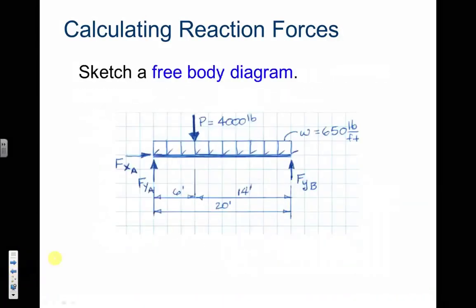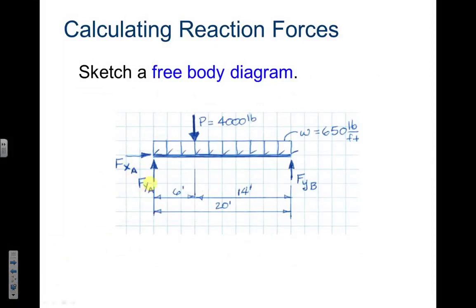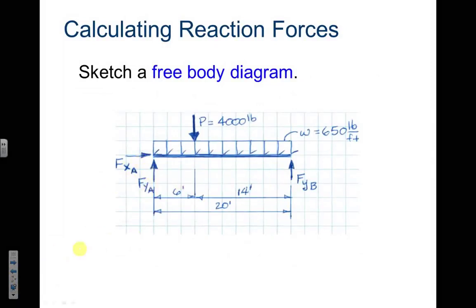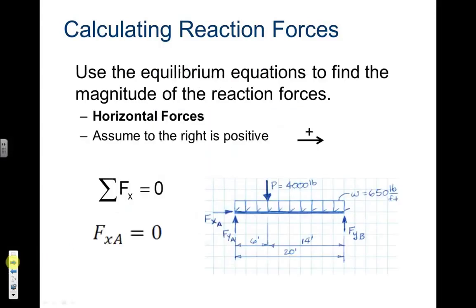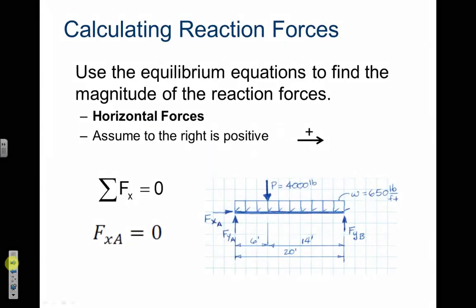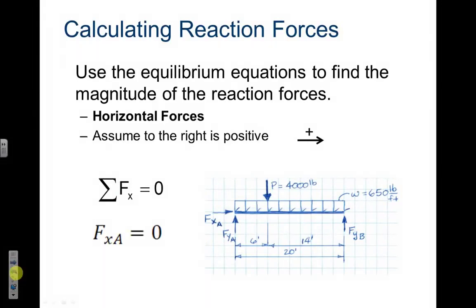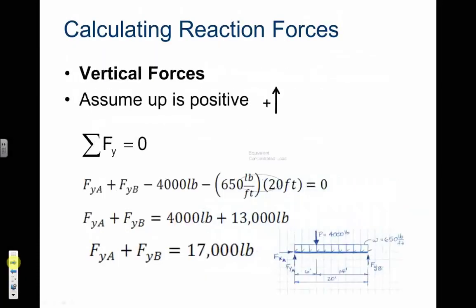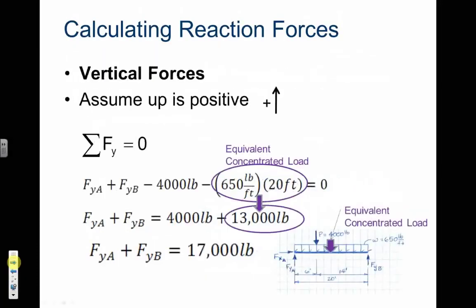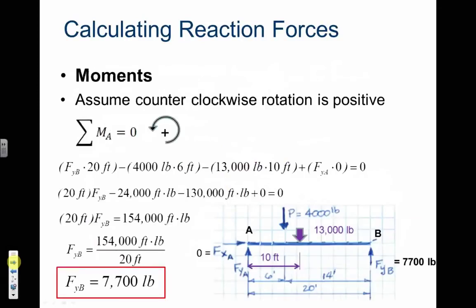Okay, our free body diagram. We just replaced our pin and our roller and drew and wrote our reactions. Okay, I'm actually going to do this a little bit out of order. I like to calculate the moment first. This is the toughest one.